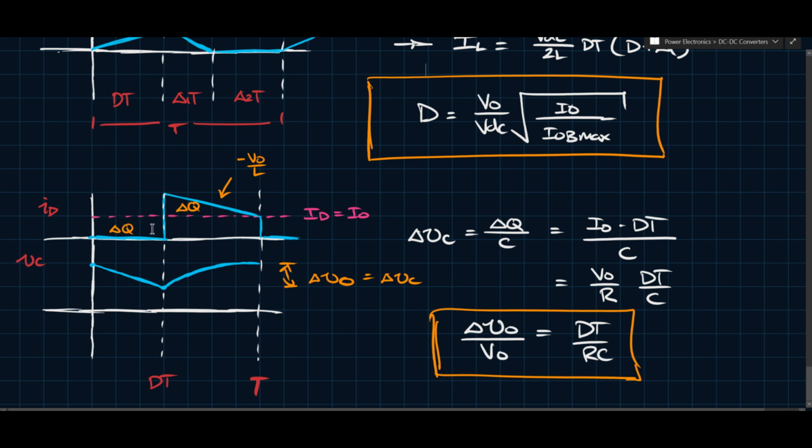It would only charge and discharge whenever you would be deviating from the average. So a positive deviation would obviously charge it, and a negative deviation in this case would discharge it. And so based on that physics analysis approach, we developed this very clean and compact expression here for the output ripple of the buck boost converter.